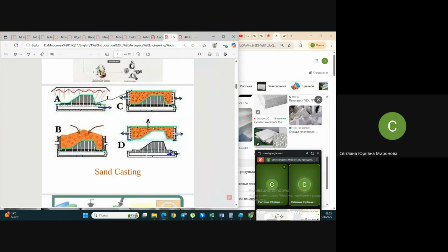What is the problem of casting at all? That inside the molten metal you have some inclusions. Those inclusions may be of solid type and they may be of gaseous type. They may be some gases. And these inclusions, during solidification, usually float up. They strive, they try to be removed.